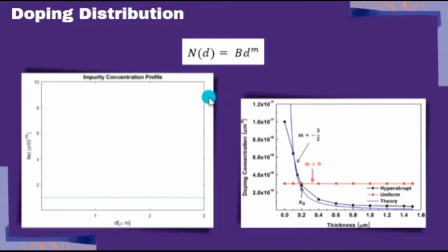Next, doping concentration is an important parameter in a varactor diode because the doping level determines the tuning range of the varactor diode. The simulation result indicates that the magnitude of impurity concentration is uniform over the thickness of the doping width, where the value of doping distribution is 10^16 per cm³. Both values from theoretical and simulation are slightly different due to the material type used in the varactor diode. However, the pattern of impurity concentration decrement over the doping width increment has been verified.